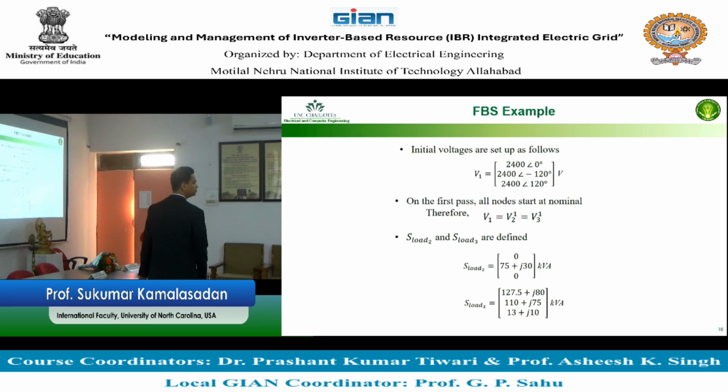How do you know? Everything is 3. Okay, these are 3. Power distribution network power flow is 3, not 1, because we have 3 phases. So is this a 3-phase load or a single-phase load? It's a single-phase load, connected to only one phase. How do you know? Because the other two numbers are 0. Which phase is the load connected to? Phase B. A and C are not.